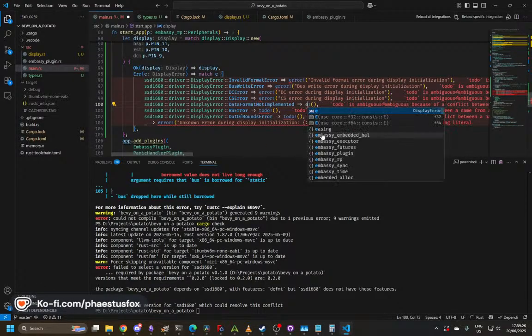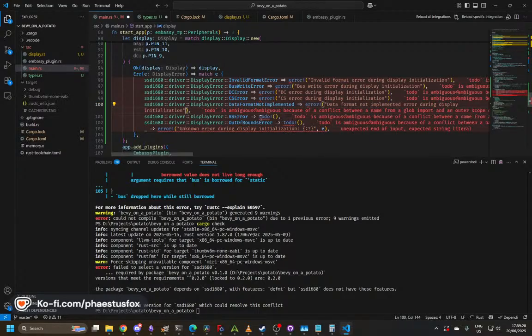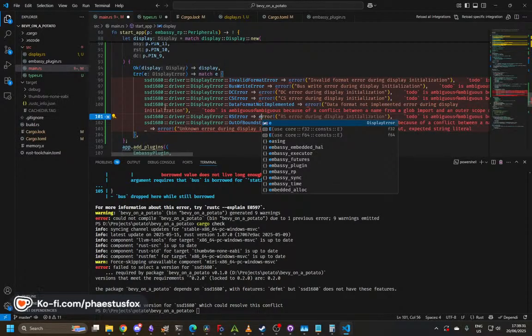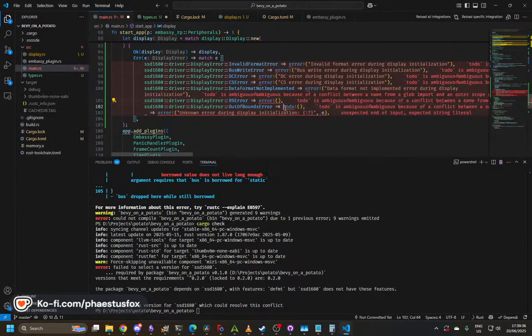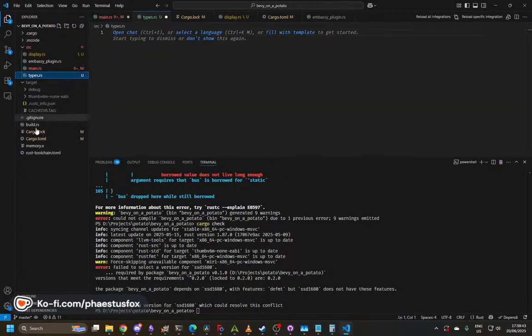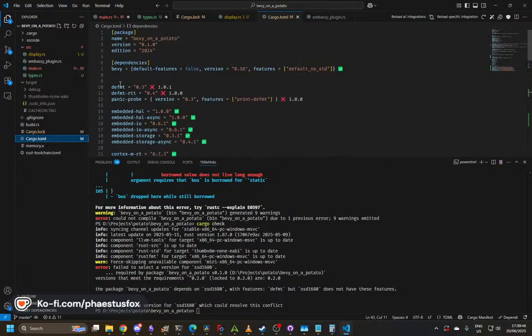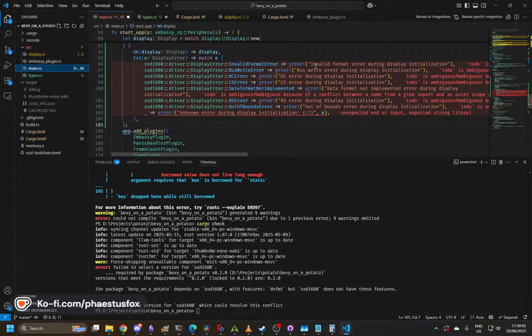This seems like a horrendous waste of space, but the whole idea of the crate, defmt, thank you. Well, we go here. This crate, defmt, is about, instead of putting these strings in the binary, it just says look up what this string is and then sends the ID of the string, and the string stays on the computer. It's not actually loaded onto the flash.